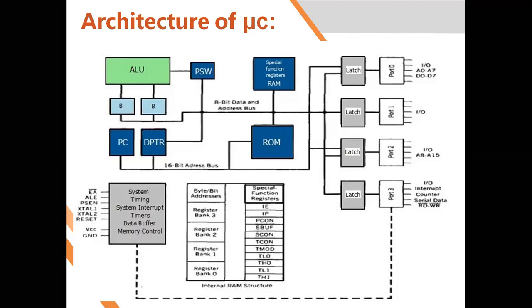As in the multiplication, nothing is carried and all that. In the division operation, your result is in the A register and your remainder is in the B register. So see here, once again I will repeat for the B register. B stands for B register. It is 8-bit long. It is used in multiplication and division operations only.